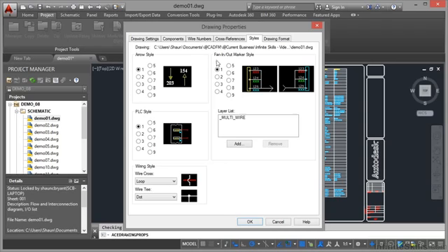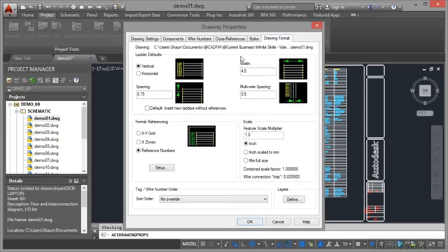If you've got any fan in and out markers as well, you've got all different styles here, you'll notice. Just select a style, whichever style you want to use. Normally defaults to 1. And your layer list is multi-wire. So that's set up in your environment variables in your AutoCAD Electrical project. And then drawing format. These are the other changes we can make when we're bringing ladders into our logic ladder drawings. We can specify all the settings there.